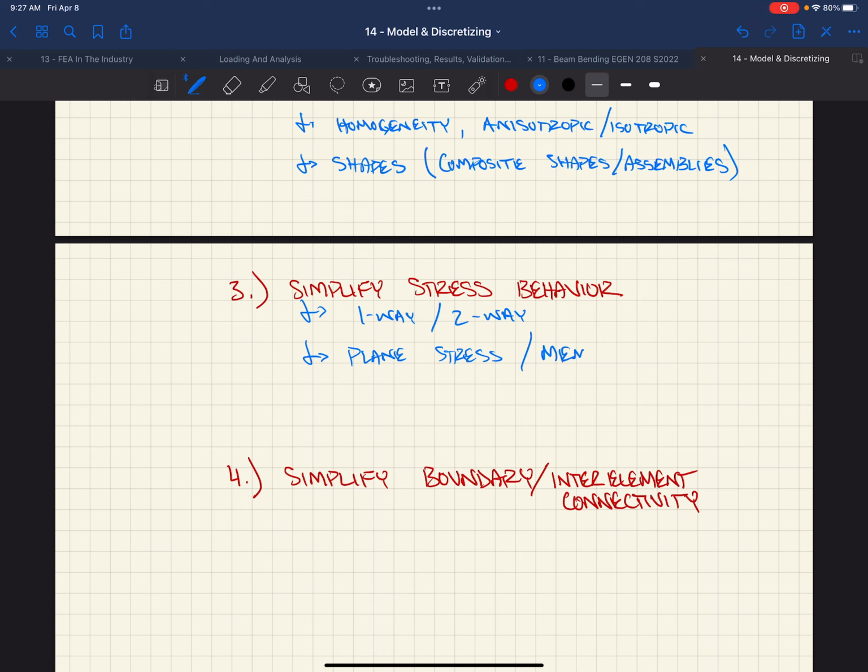Or we called membrane action, right? Obviously, if we're designing, say we had a cast-in-place concrete diaphragm, and we put it out on this plan view, right? We had this grid system, we have this concrete on there, and we were actually designing the diaphragm. We probably want to make sure that we don't assume that it's a membrane, right? But if we were designing, say, the brace frames, say there were 2 brace frames at the ends of this building, right? And now we're looking at this diaphragm, we're going to model this diaphragm, but our interest in this model is to design these brace frames.